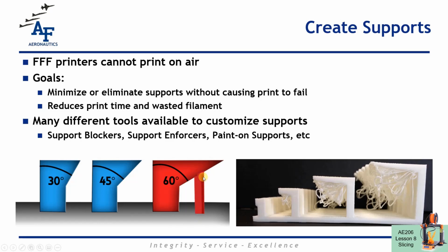This is where the discussion of supports comes in. So this is a support tower here that's helping to support it. The only bad part about this picture is this is a 60-degree angle everywhere here, and so everywhere would need support, not just this one place on this overhang. For a 90-degree overhang without supports, the printer is just extruding out a bead of plastic on thin air, and that bead of plastic is going to fall down, and then the printer is going to go back to extrude the next layer out, and that layer is going to fall down.